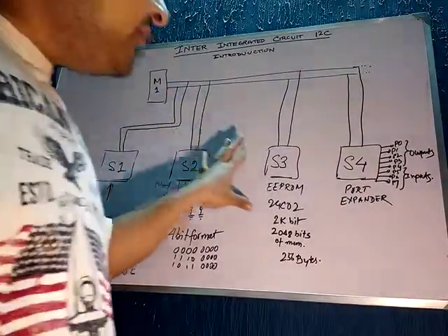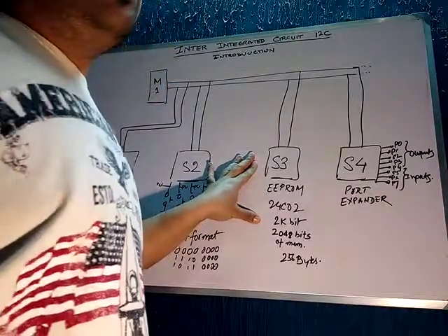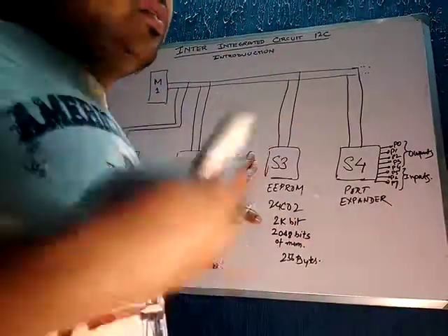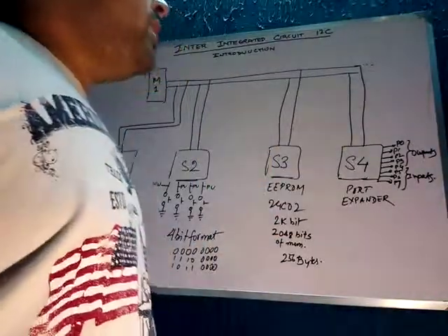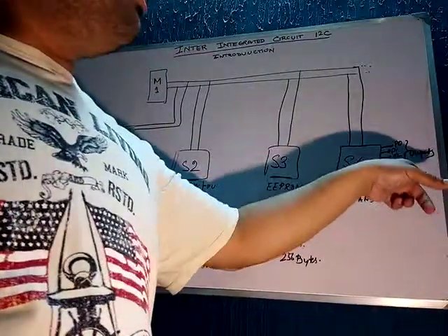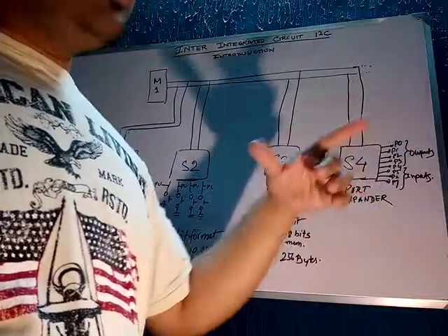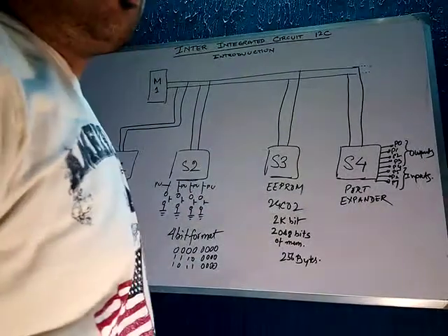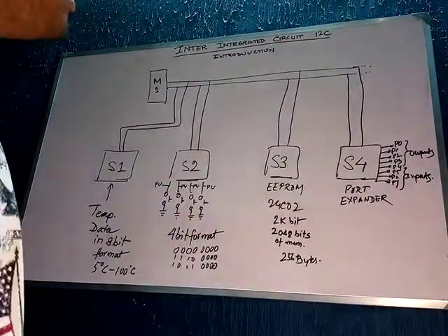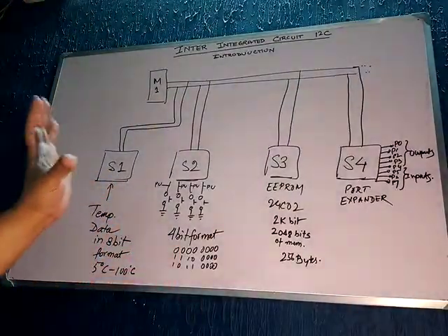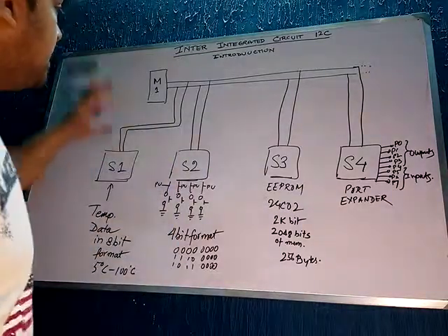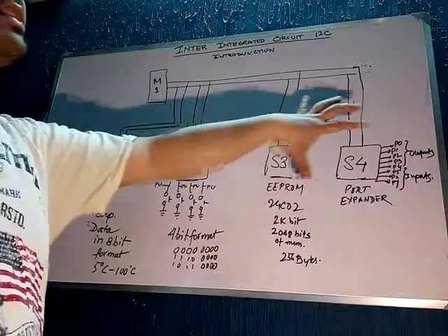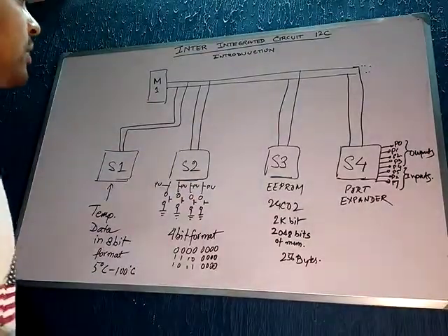It has to save the user's temperature requirement, and accordingly take input from some other sources, and accordingly it can switch on some fans or some heaters. Now this is where I2C communication comes into the picture, because the master has to communicate with multiple slaves, but it has only 2 wires.